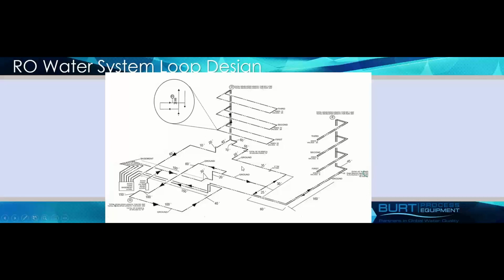As another example, a serpentine loop is what you see over here, where the water just comes out and comes back in as one primary loop. It's not very practical if you were to run this as one giant loop. Every one of these floors would go back and forth, and then you have a very large diameter loop running through your entire building at that point. So there's definitely practicality in designing your loop with more of a ladder loop design.